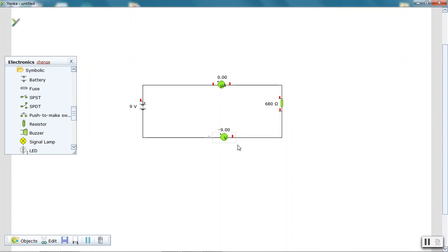And you'll see the voltmeter is reading negative because this little black square is indicating the positive end of the voltmeter. So I actually have the voltmeter hooked up backwards in comparison to this battery. But the main thing is my ammeter is not reading any current.